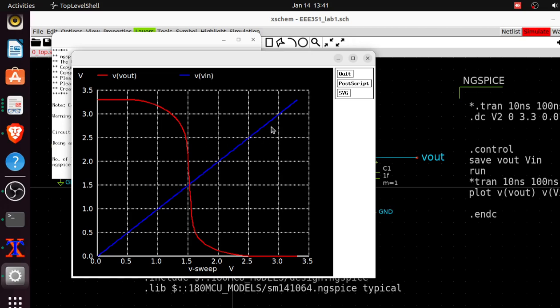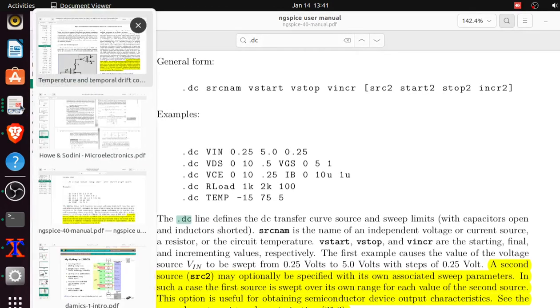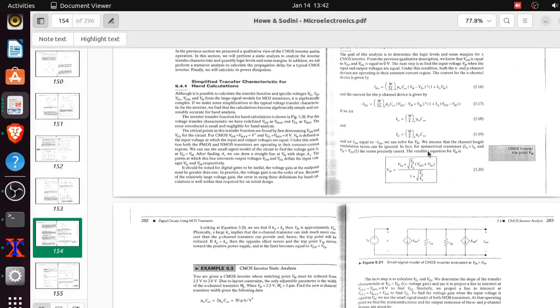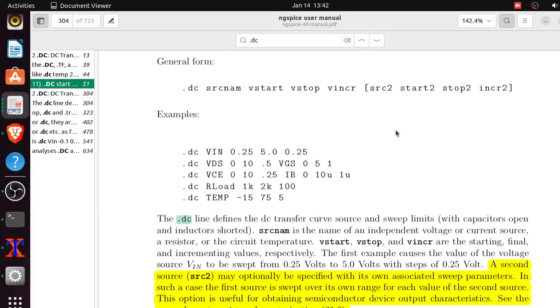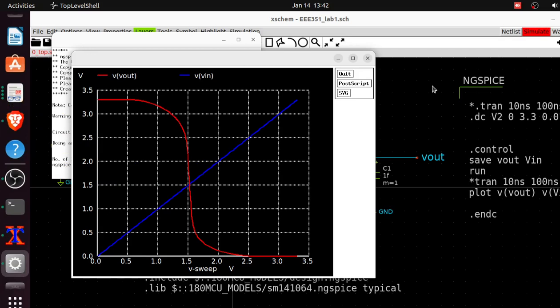You can confirm that using this formula for the switching voltage. For SkyWater, you can check the Spice file to approximate the threshold, then the transconductance parameter and the sizing. We just put everything in there, and I think we'll get approximately 1.6. So that's the switching voltage. Let's do a little experiment, then that will be all for the DC sweep.